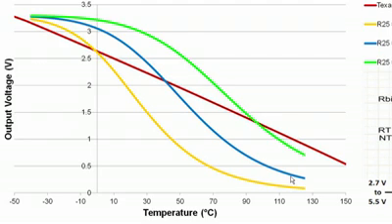The saturation at low and high temperatures may cause temperature errors due to the resolution of an interfaced ADC not being high enough to detect a change in output voltage per degree Celsius. Thus, engineers may have to use a higher resolution ADC to account for this error. This is a problem that is not seen with analog temp sensors, as they have a virtually linear output.